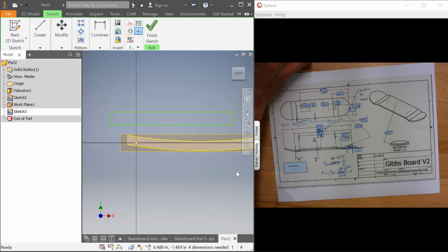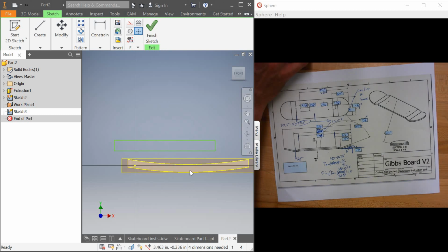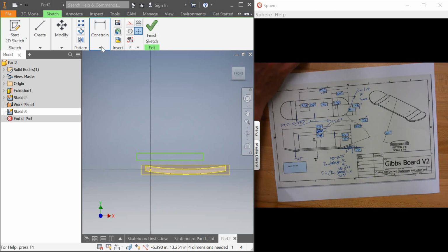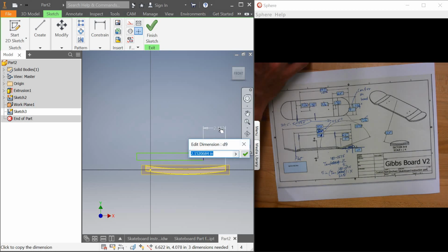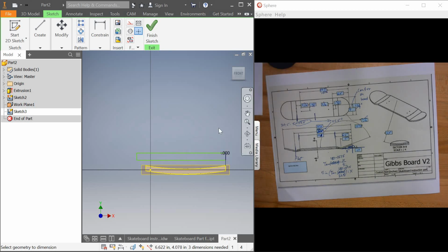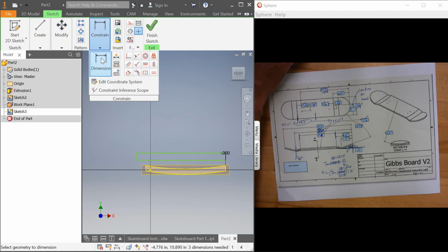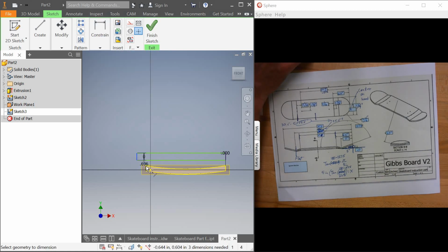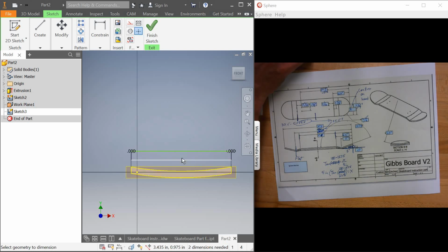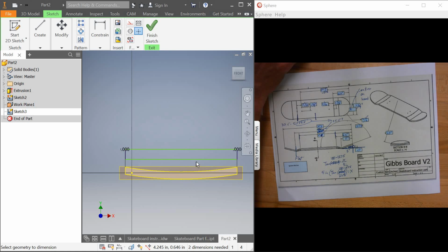Okay. And so I do my rectangles off of the drawing. And the reason I do that, again, is because I want to put my own measurements in so that once it's measured up, once I know that, because I know it's wrong right now, and once I measure it to something else, I know that my measurements are correct. Okay, so I'm going to hit constrain, and I'm going to hit that measurement there, and it should line up exactly, which means there's a distance of 0 in between them. Okay, so we're going to hit dimension, didn't have to do that again. All right, I'm going to hit a 0 there. So now I know it's lined up on the sides, right? I know my dimensions are lined up.